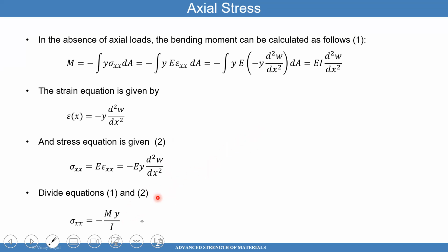And what that's saying is at the neutral axis where y is 0, you have no stress. But in the outer fibers, farthest away from the neutral axis, you get the highest stress possible. Any questions on that? Stress derivation. That's the equation you'll be using.